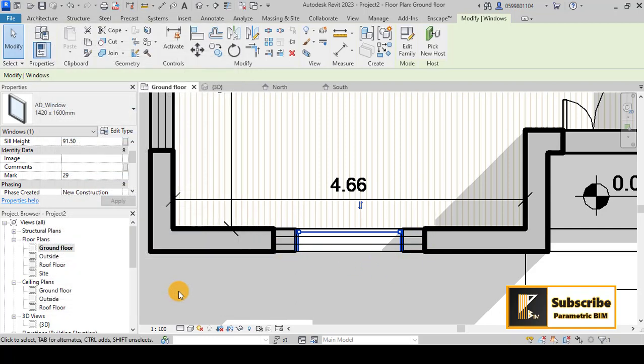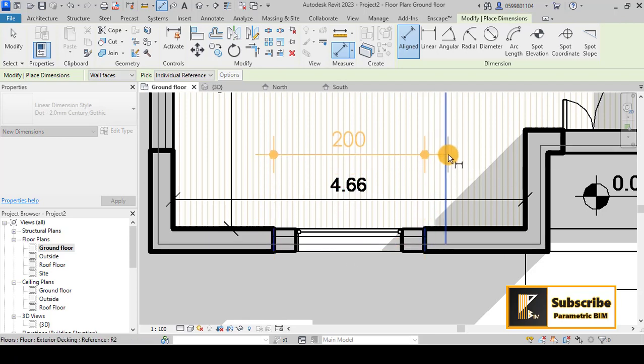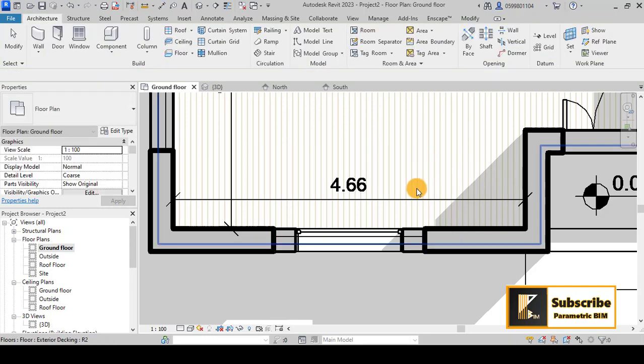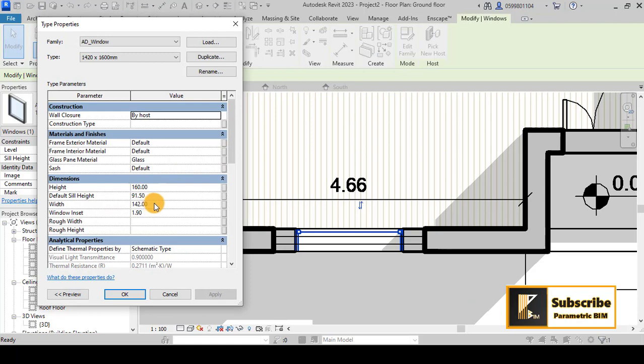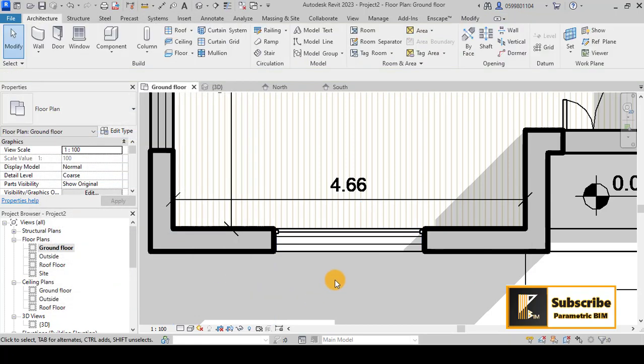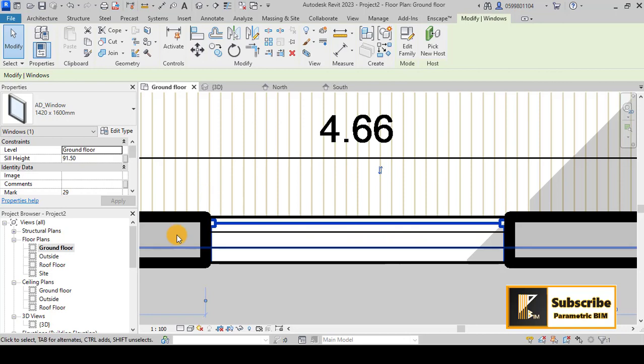So I will go back and then go to annotate, and let's measure from here to here to see that our window is 2 meter or 200 centimeter. So I will go back, click on the window and edit type and give 200 centimeter for the width. And as you see, our window automatically came to fit the opening that we have.